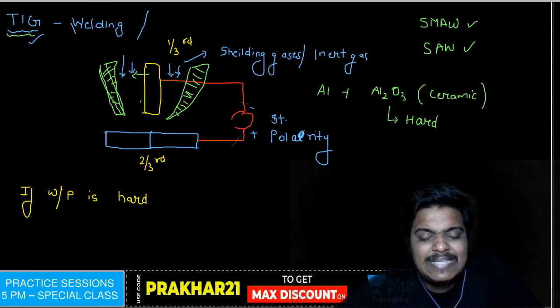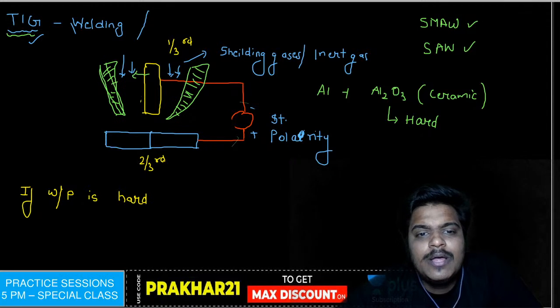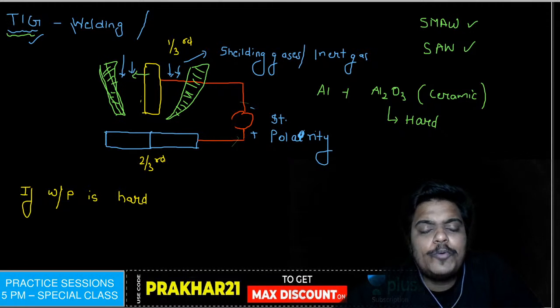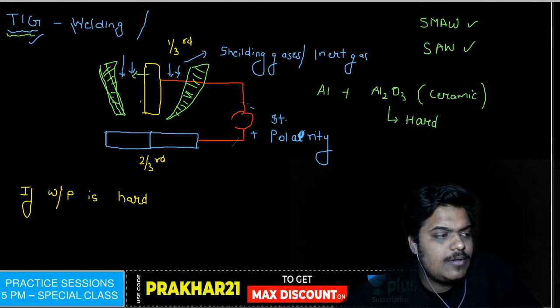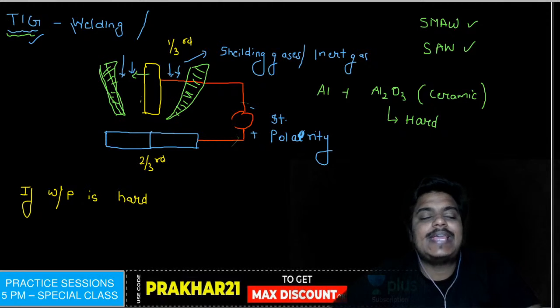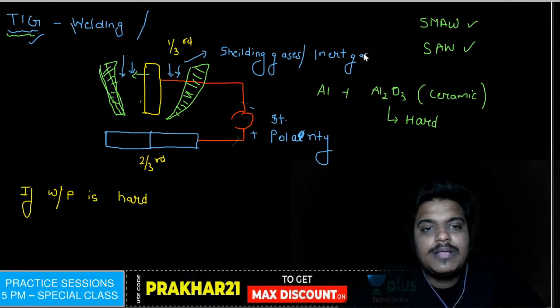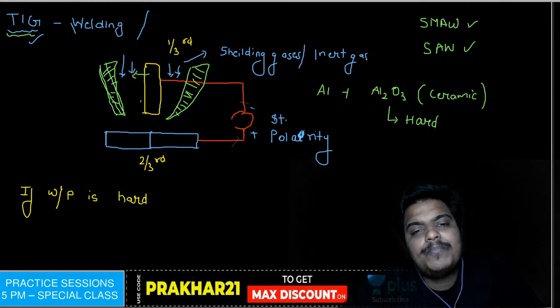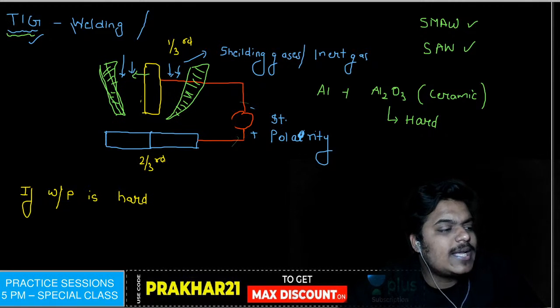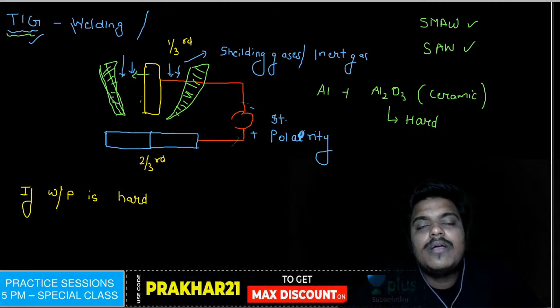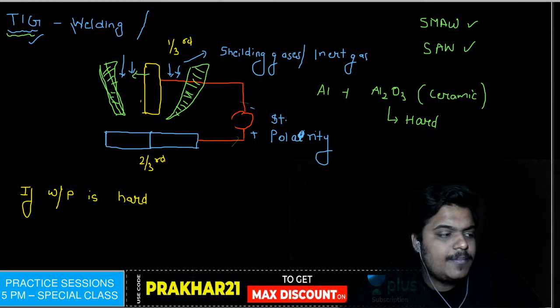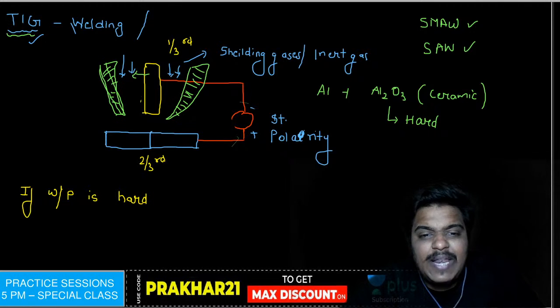Quickly tell me. Yes. Since the electrode is not consumable, we will use a filler rod to fill the gap.